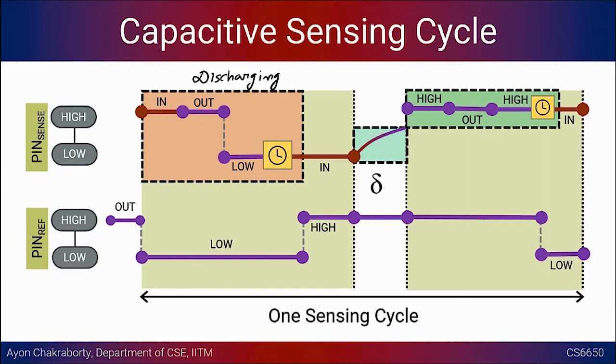Once we keep on reading this pin, it becomes digital 1 at a certain point in time, and we put some extra amount of time, since the voltage of that particular pin was not exactly 5 volts, so we put some more time for charging that particular pin. So it was sort of discharging and charging a particular pin in our sensing circuit, right?